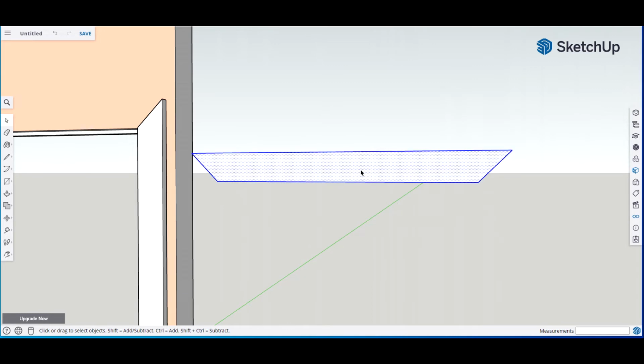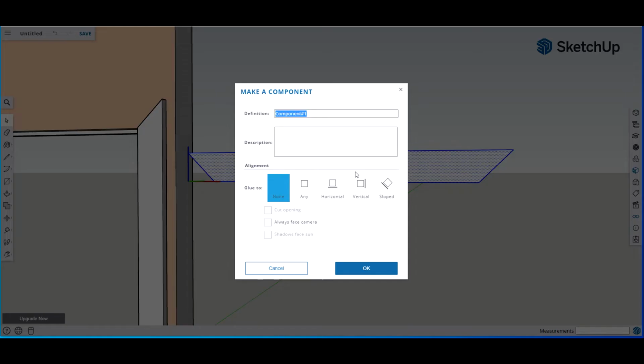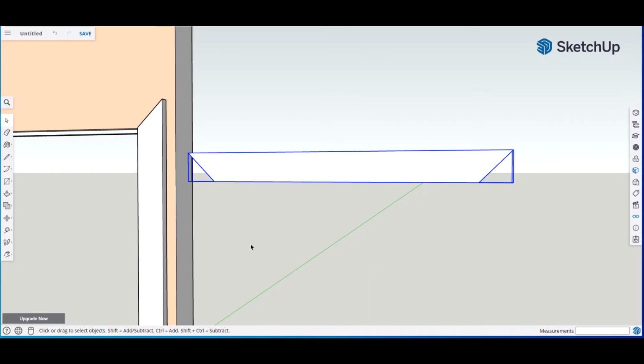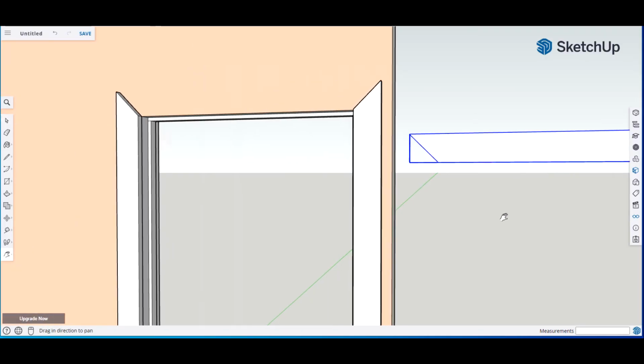I'm going to triple click this anyway, hit M, and just move it a little way. Free space, click it again, push pull, bring it towards me, and we know it's 15/16 of an inch. Got it. Triple click, and we're going to call it top door. I always call it top mold. And hit OK.